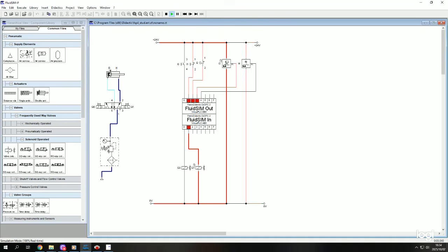Already my rear end position sensor or detector, there's current flowing to show it's active. So meaning the piston rod is at its rear end position. So I click my push button, it advances. Then when it's fully advanced, my second I4 will have the same arrow, and these lines will be dark red or bolded to show there's current flowing when it's fully advanced.